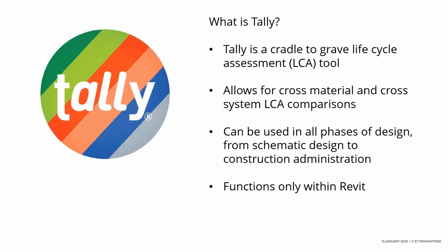The same would not apply if you had EPDs, because there's different rules that are used to generate each EPD, different assumptions that go into those rules, things like that. And as a result, it makes it very difficult to compare across material types. But that's the benefit of a full LCA tool that uses a single process database in the case of Tally.